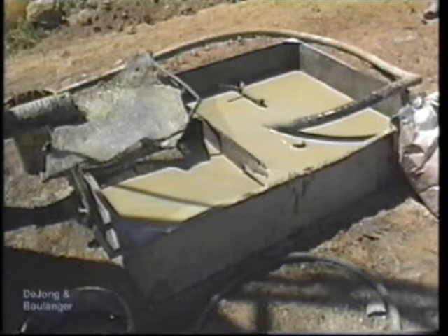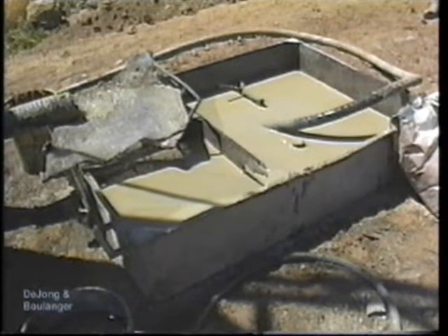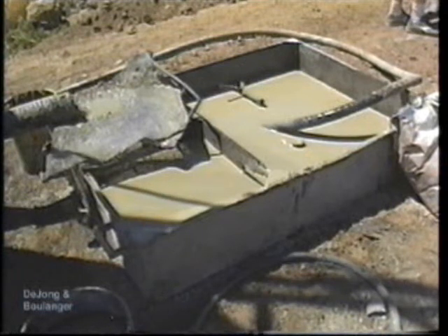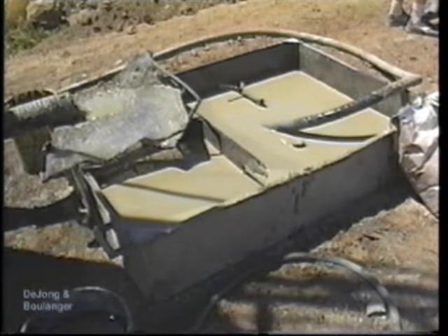The mud is a mixture of water and bentonite, which creates a slurry with a density slightly higher than that of water. This higher density helps in the removal of cuttings, preventing them from settling on the bottom of the hole. It is important for the slurry to have the correct consistency. If it is too thick, it can clog the pump, and if it is too thin, it can leave cuttings at the bottom of the hole.